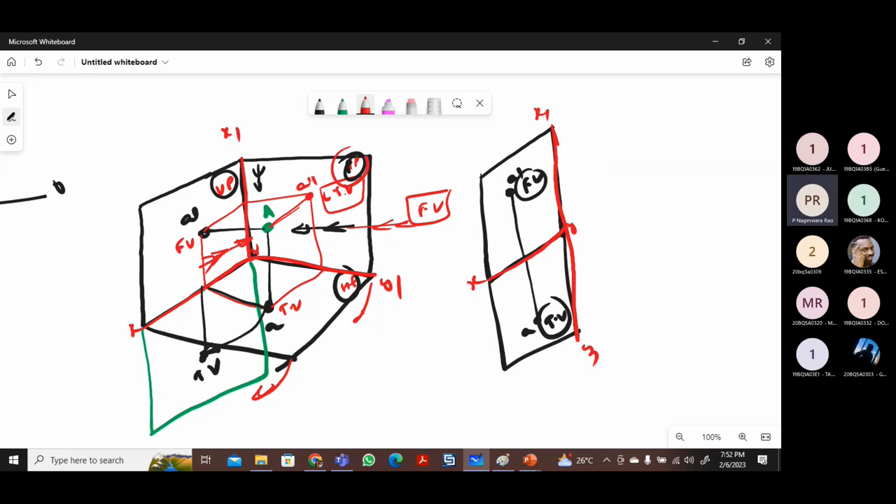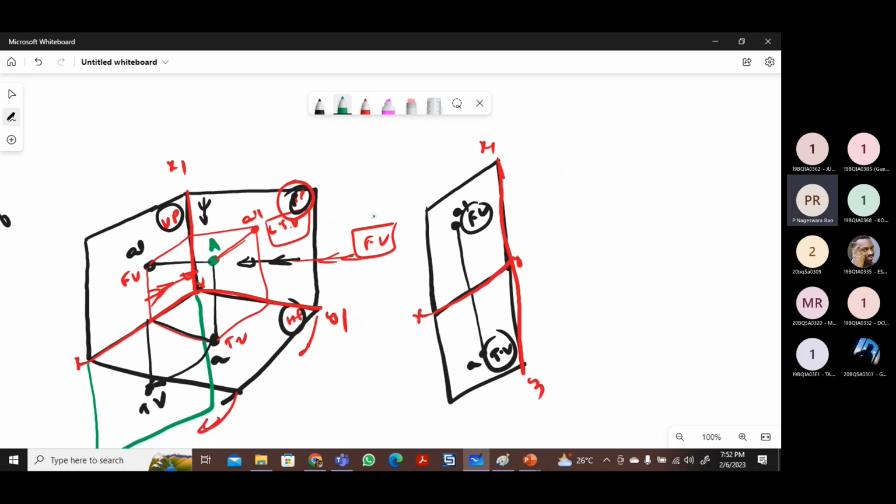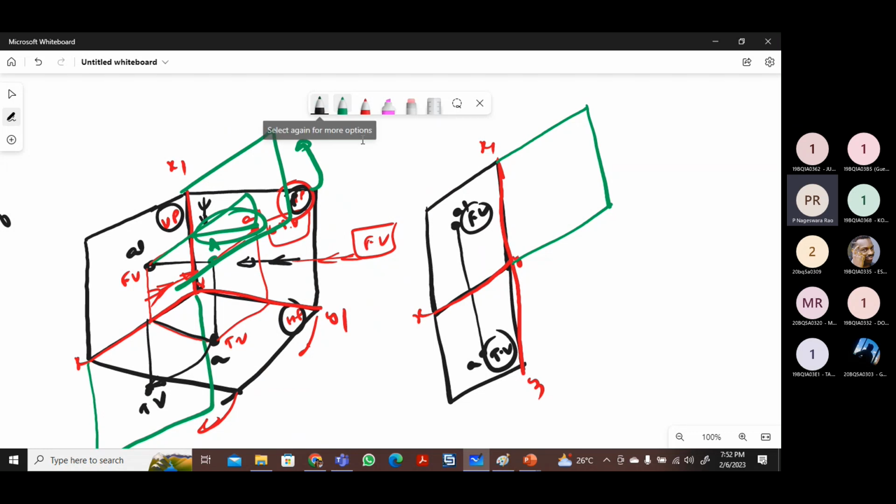So when you rotate this profile plane also like this, I need the horizontal plane towards the downside. We need to rotate like this, so the plane will come here. I am drawing this one like this. The profile plane will come like this. So this left side view image comes here, exactly beside the front view. That means if you observe, the side view is always beside the front view.